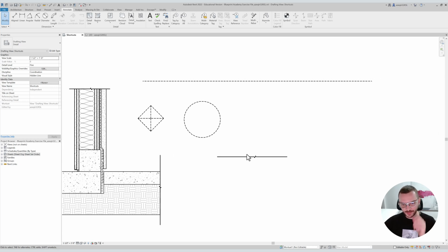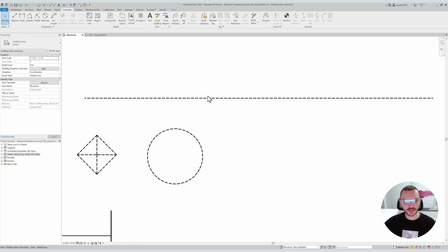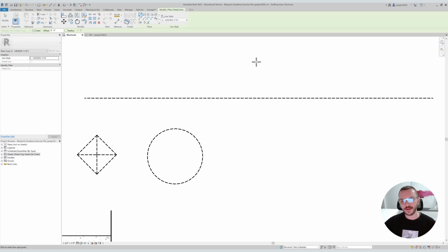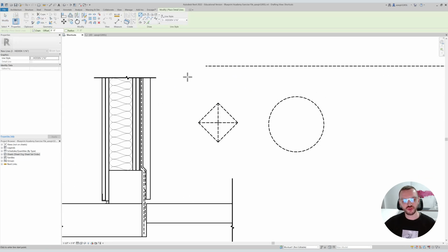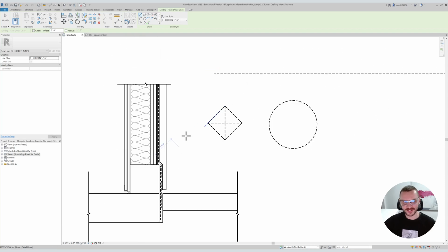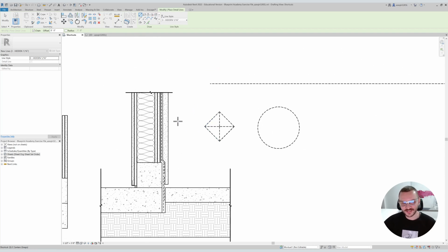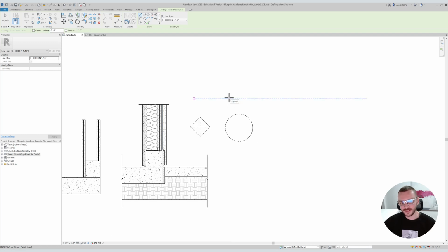So let's talk about snapping real quick. Let's say you want to draw a line here at this corner, right? But you don't want to zoom in and be all like, oh my god, I need to go in there. Let's say you just want to do it fast. You just go in here, hit SE, and then go to wherever you want. As long as you're on this half of the element that you're selecting, it'll go to that endpoint, right? So here, endpoint, endpoint, endpoint.